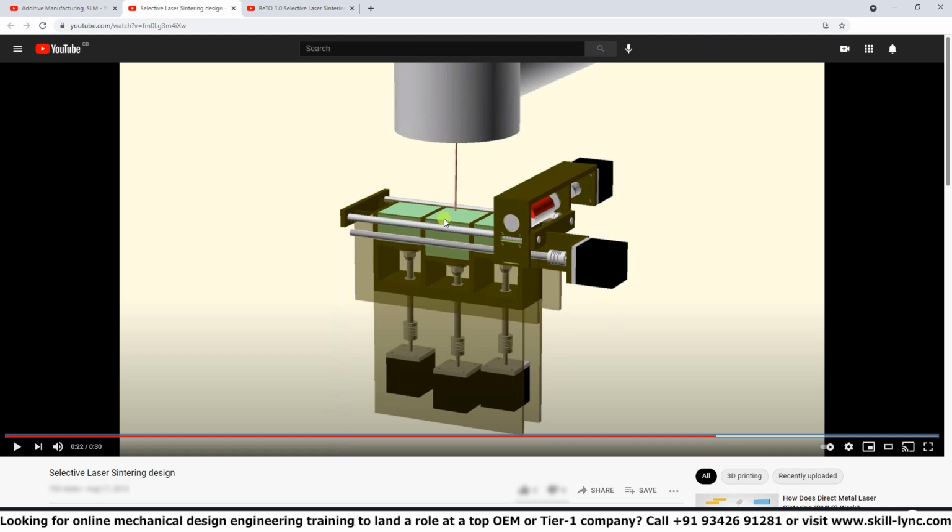So obviously we're discussing both selective laser sintering and selective laser melting in this one example, because even though there are two technologies, the main difference between them is how much of the powder you melt. Selective laser sintering actually uses a sintering process rather than a melting process.